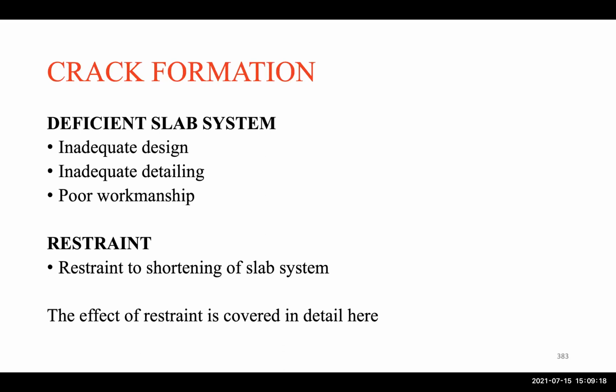But it's extremely important to watch for these things, cracks, which may lead to other things, to corrosion in the reinforcement. If there's corrosion, of course, there is a reduction in the rebar area, and if that's not maintained over time, disasters will happen.